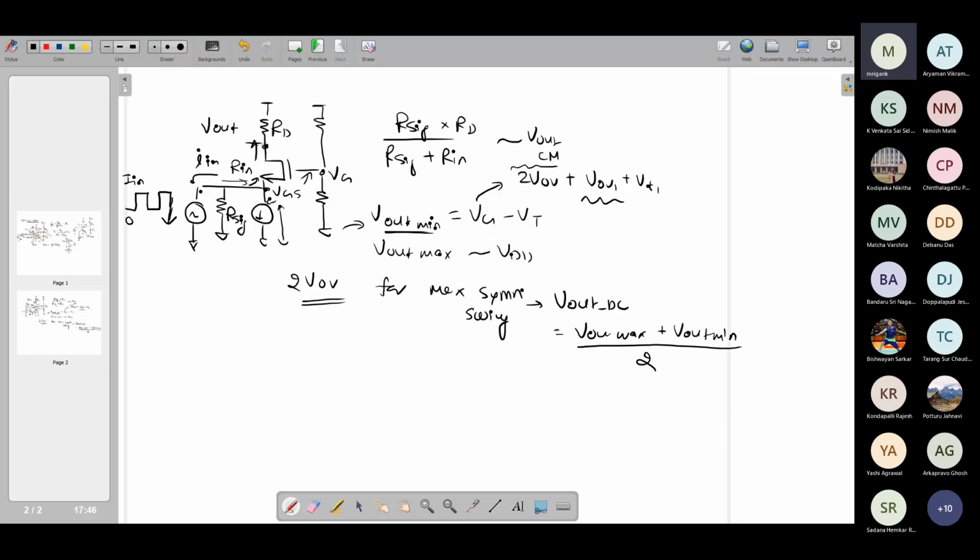So I have to be careful because whenever I'm drawing the signal current, it is going to reduce the output voltage. And therefore, if the signal swing at the output is too high, if I'm making RD too high just to get more gain, it will lead to this transistor entering into triode region.